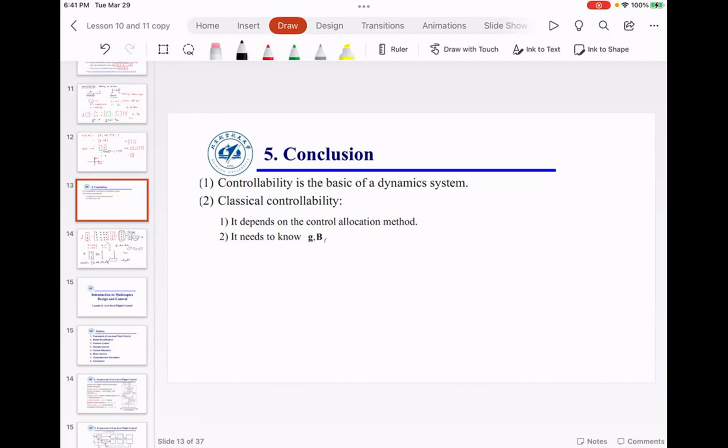Controllability means that by an external forcing function, you should be able to influence that state. If you can't influence that state, basically you do not have any control. That is what controllability means. And the rank condition talks about independence, and it essentially says whether the control function is able to control the entire state space or just part of the state space.